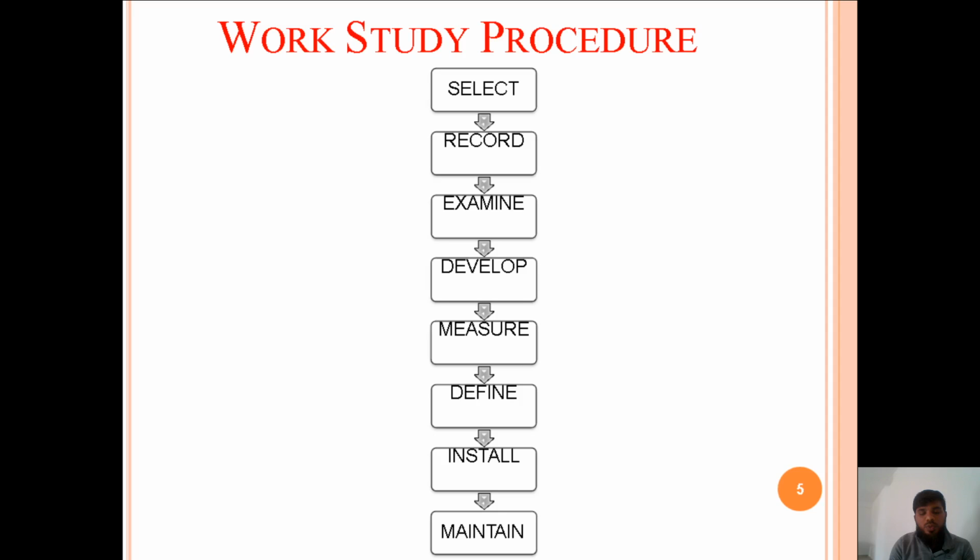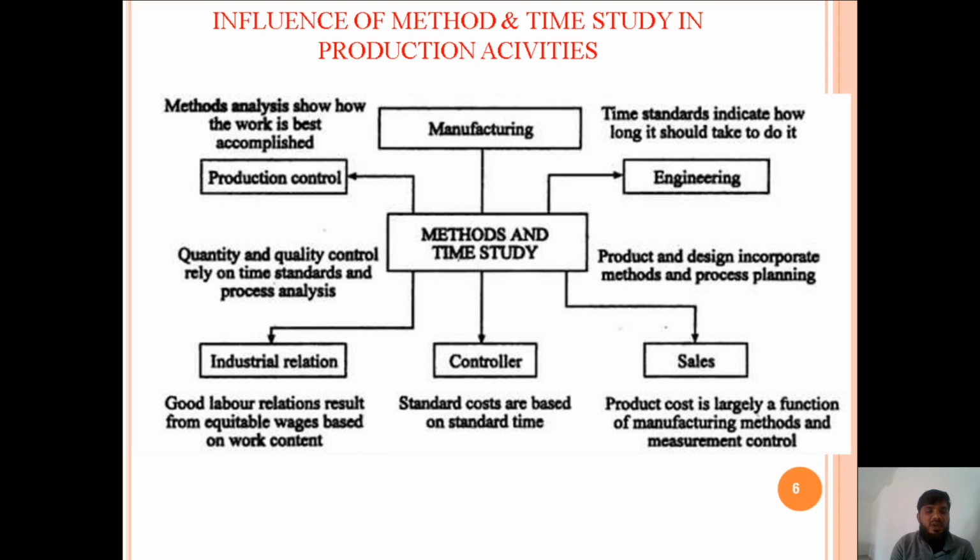In this, what I can do is arrange a conveyor belt in front of the laborer, where the belt will be going in front of him, so that he can directly lift the object from the conveyor belt and put it in. So the time reduction can be achieved, and the method can be done easily. When he keeps doing the repeated task of getting down and up, he will get fatigued and lose his strength to do the work.